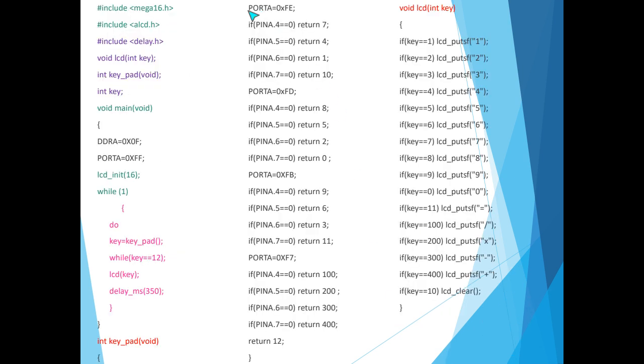So PORTA is equal to, at first I configured PORTA as 0xFF. But because at any given time they are becoming 0 respectively, I make each of the bits 0 and then read the pin related to each of the keys. Okay, PORTA is equal to 0xFE.